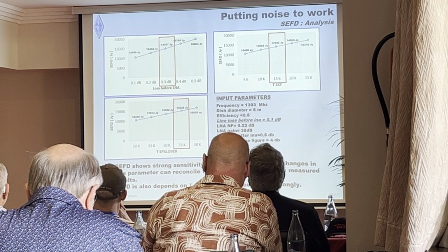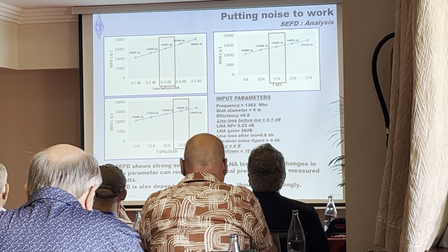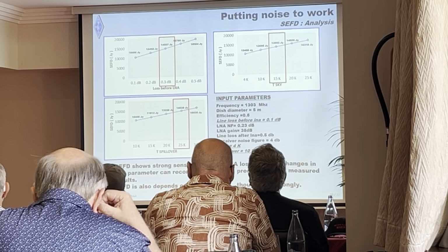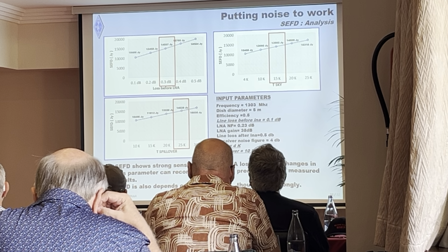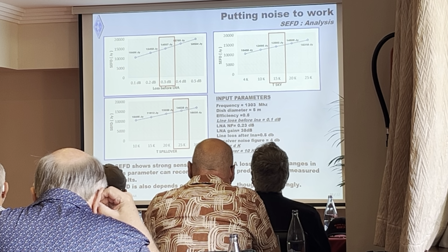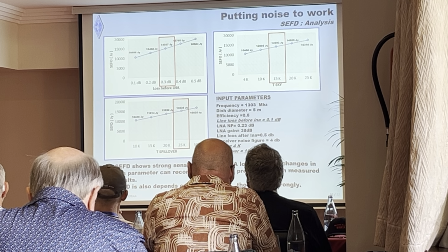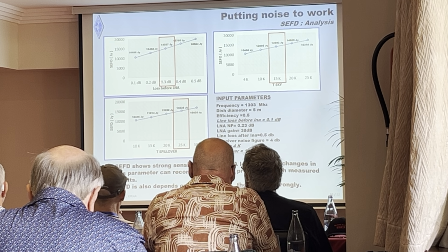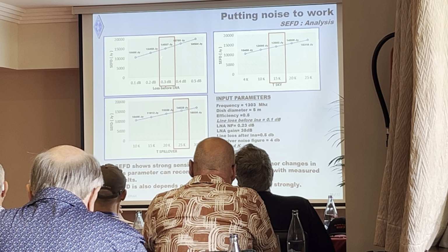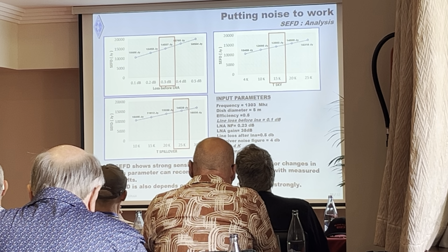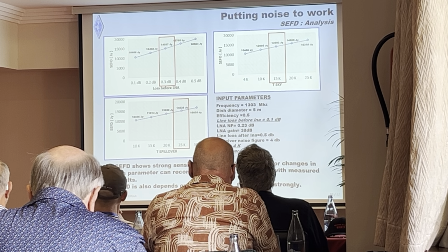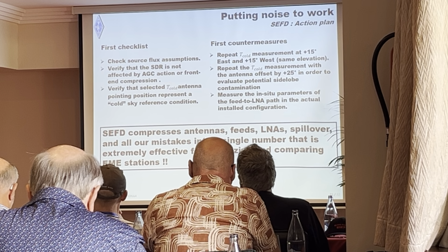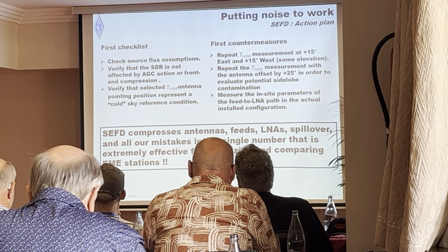I found that the influence of the loss before the LNA, as Casa was telling us, is really big. In my system, I put 0.1 dB, maybe that was not correct. Just moving to 0.3 dB, I am exactly at the SEFD I was calculating. Very interesting, because we can play with this number, and playing with it, you can come to a kind of